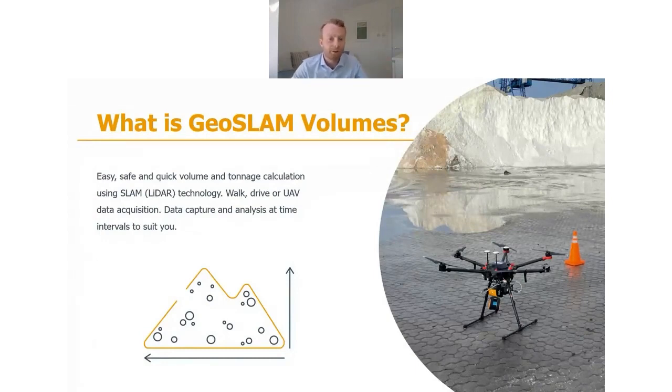Once that data has been captured, the user can bring the data off the scanner onto their PC, and the GeoSLAM software package using GeoSLAM Connect and GeoSLAM Volumes will do the rest. It's an automated process from start to finish without the need for any user input. The user will be provided at the end of the workflow with a tabular and graphical view of their volume and tonnage calculations, and this will allow stakeholders to easily make informed decisions on their stockpile asset.